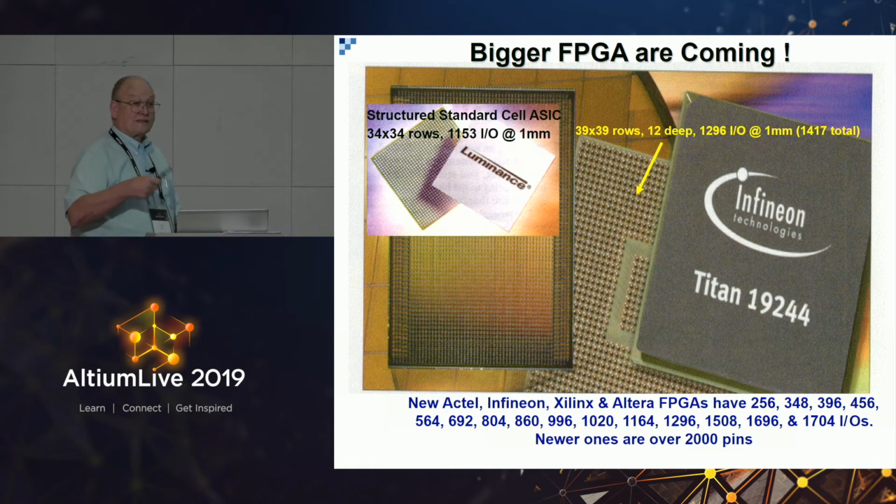One of the tenets that I'll show you over and over again is that if you use HDI properly, your complex PC boards will cost less, not more. But the conventional wisdom is, well, if you're going to use HDI, be prepared to pay 20% more. If you do, you've done it wrong. If you do it the right way, you'll pay 20 to 50% less.